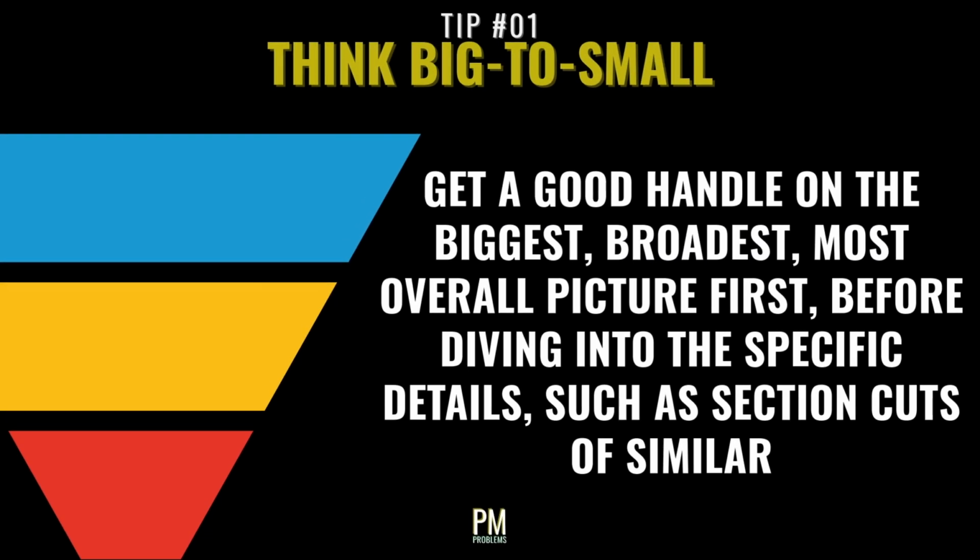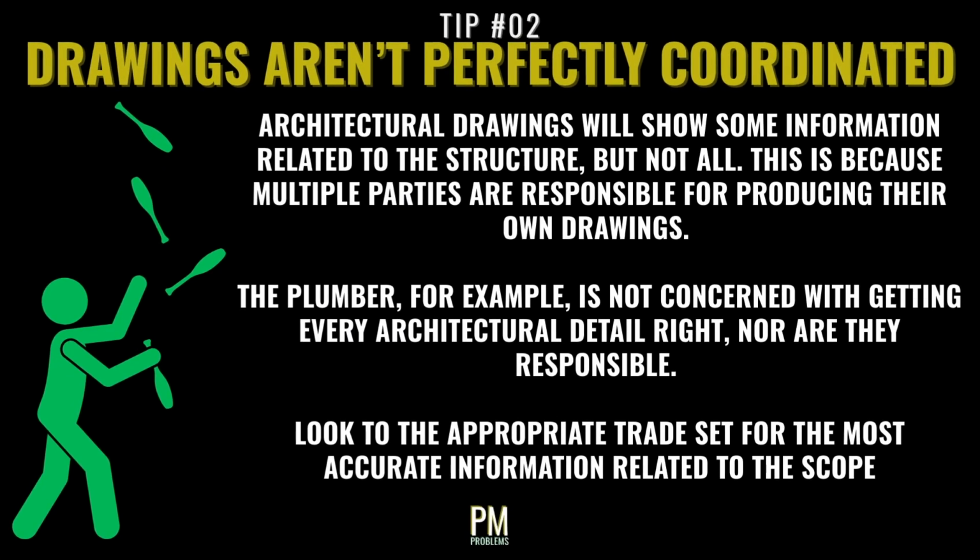I recommend getting a good handle on the biggest, broadest, most overall details first before diving into any of the specific details such as section cuts, etc. It's also important to understand that drawings are not perfectly coordinated. Architectural drawings will show some information related to the structure, but not all. This is because multiple parties are responsible for producing their own drawings and the details relevant to the portion of the work that they're handling.